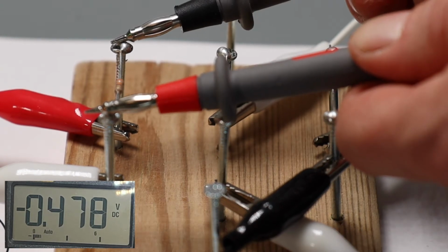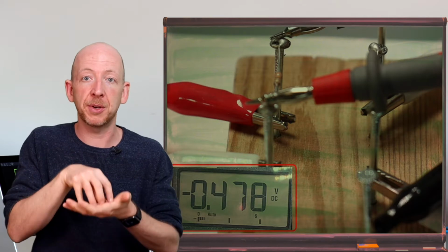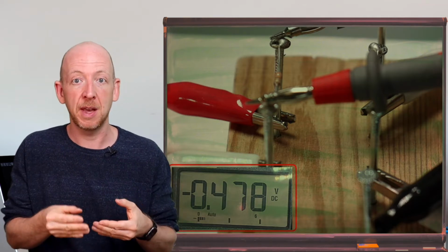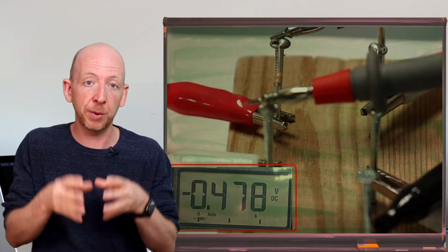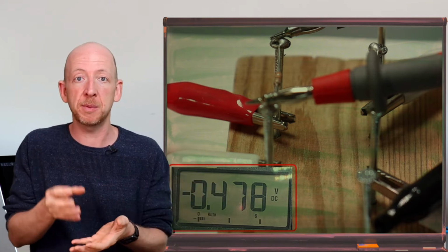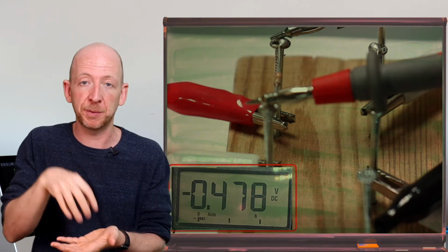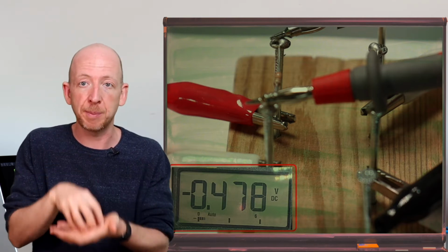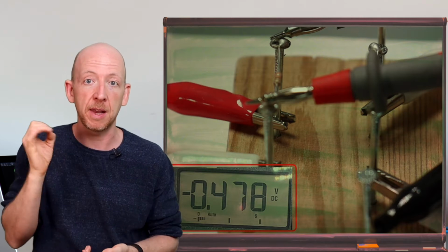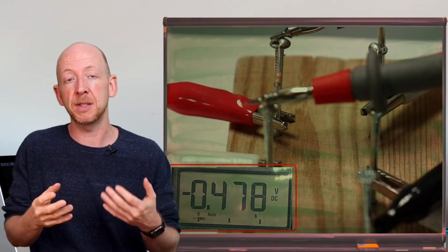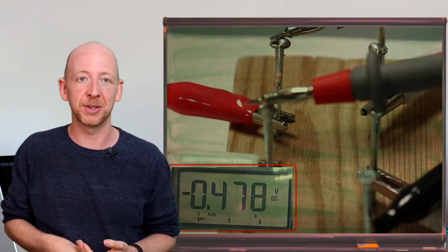And from the display we can read a value of minus 4.78 volts and the negative sign, which you might have noticed, by the way, this comes from the fact that I have connected the COM port of the voltmeter to the positive terminal of the source. Actually, it should be the other way around, but we are only interested in the amount of voltage at the moment, so the sign doesn't matter yet. It will matter later in other experiments, but for now we're only looking at the absolute measurements here. And by the way, the left resistor has a value of 328 ohms, which we have already determined previously in the video on Kirchhoff's first rule.